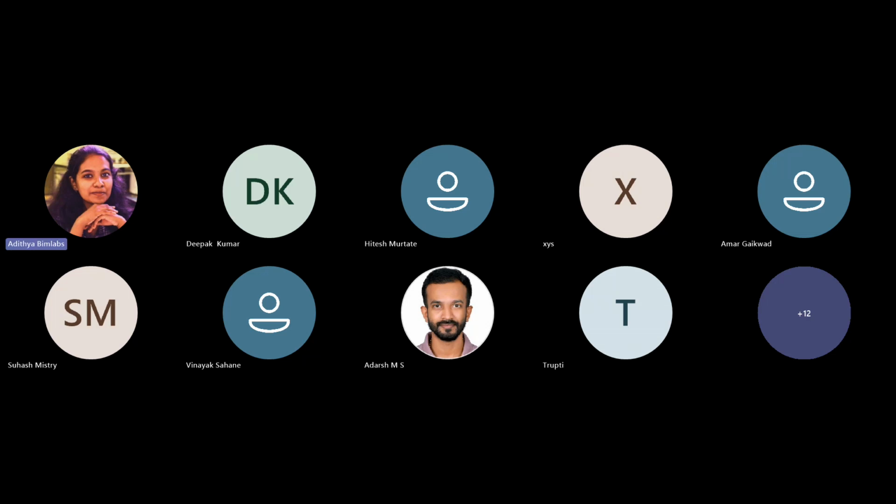Autodesk Navisworks is an advanced project review and coordination software widely utilized in architecture, engineering, and construction. It is designed to support multidisciplinary collaboration by enabling the integration, analysis, and review of 3D models from various platforms. The four main purposes of Navisworks Manage software are: first, clash detection; second, 4D simulation; third, quantification; and fourth, animator and scripter.